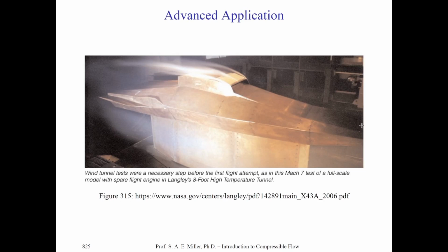So the flow moves from lower right to upper left in the wind tunnel, and it turns through turning angles, and an oblique shock forms, and it moves along and hits the cowl. And it bounces around the shock waves inside the duct, and then the duct expands again, creating expansions. They inject fuel in here and burn it through combustion, raising the total pressure and temperature, and the remaining part of the flow, even outside the nozzle here, is designed to reaccelerate the flow and create thrust.